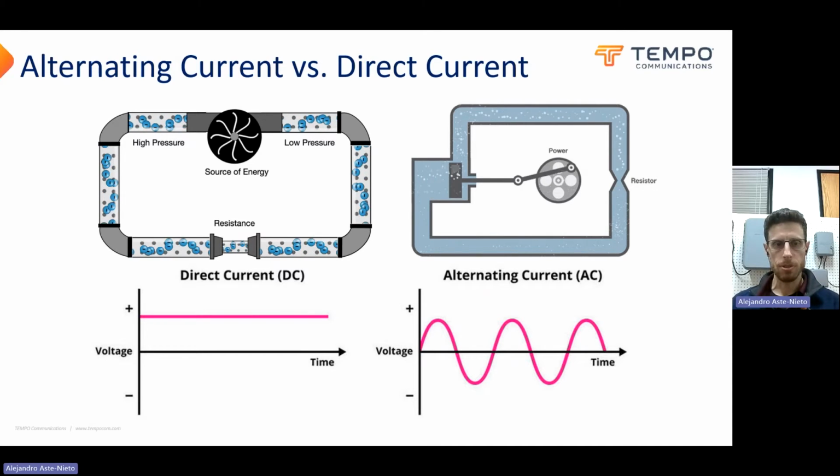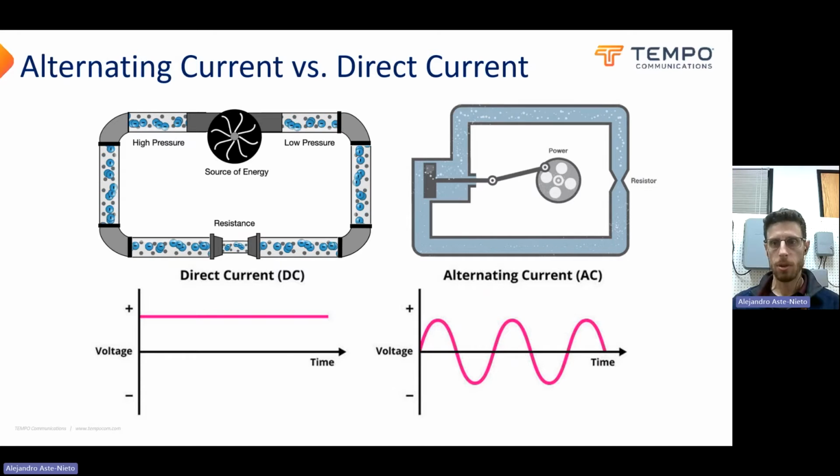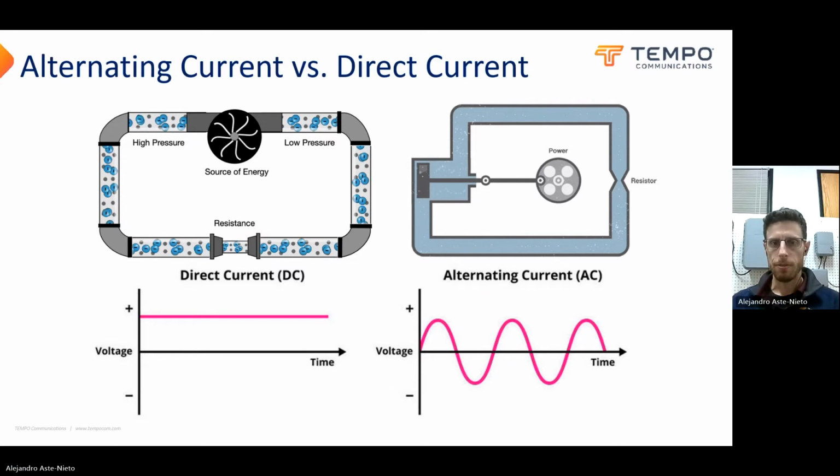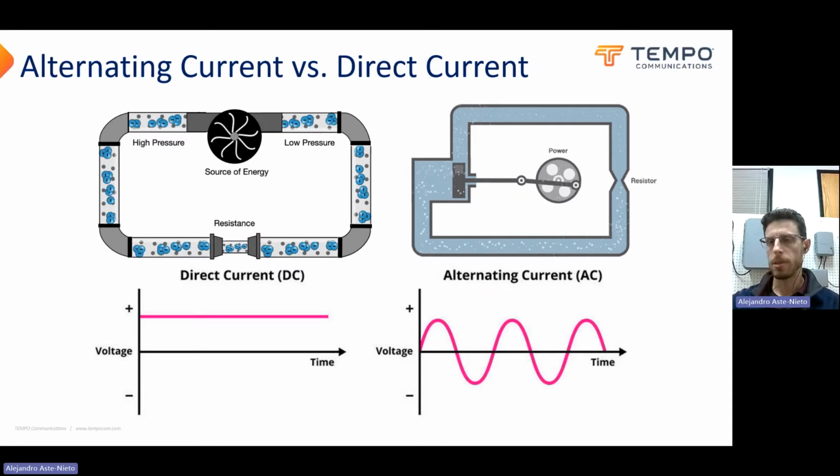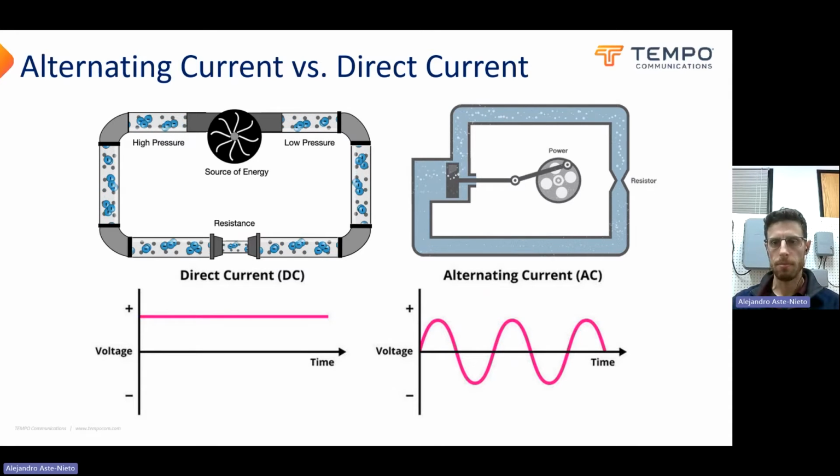If you measure volts, you have to know whether it's AC or DC volts, because a multimeter is going to be checking for completely different things here, right? Constant pressure versus oscillating, moving pressure. Same goes for current sometimes, although current is a little bit easier to sort of calculate one or the other.